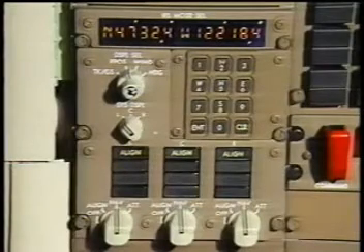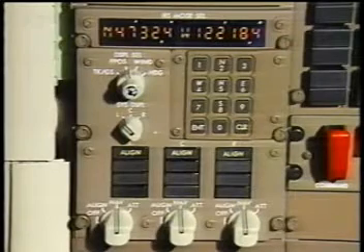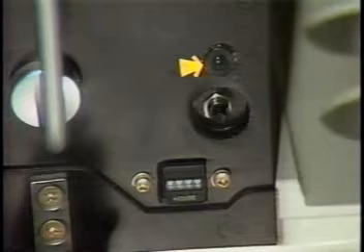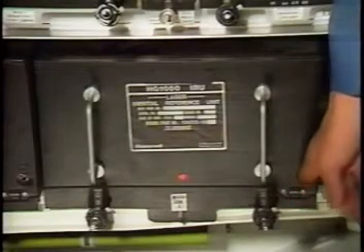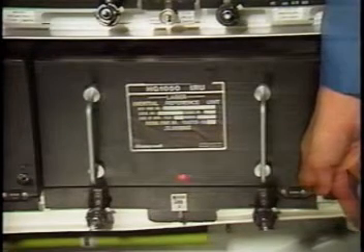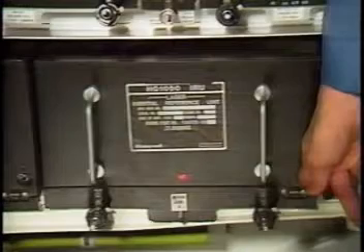The Inertial Reference Mode panel, or IRMP, should be in the nav or align mode. The test has no effect on the IRU fault ball, which remains black. Press and hold the IRU's front panel-mounted test switch until all desired IRMP and flight deck displays have been observed.